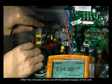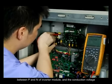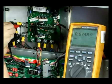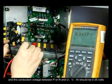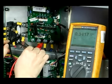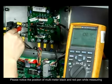After 5 minutes since cutting off the power supply of the unit, use the diode range of the multimeter to measure the conduction voltage between P and N of the inverter module, and the conduction voltage between P or N and UVW. The conduction voltage between P and N should be 0.7 volts, and the conduction voltage between P or N and UVW should be 0.35 volts. If the measured value is 0 or infinite, that means the module has been damaged and needs to be replaced. Please notice the position of the multimeter black and red pens while measuring.